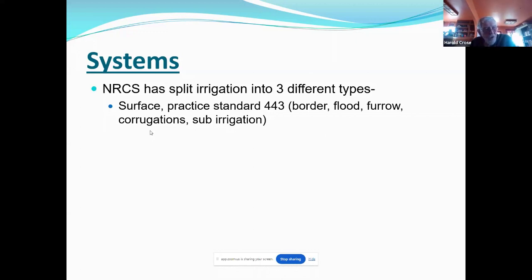So we try and get growers to get into things like surge irrigation, where you push the water as far as you can over a set period of time, maybe 6 hours, and move, and then come back to it and keep pushing it through. With cablegation and surge irrigation practices, you can push that up to 60–65%, but it's labor intensive. And that's one thing that we'll talk about all through this: labor is an important consideration in irrigation water management.